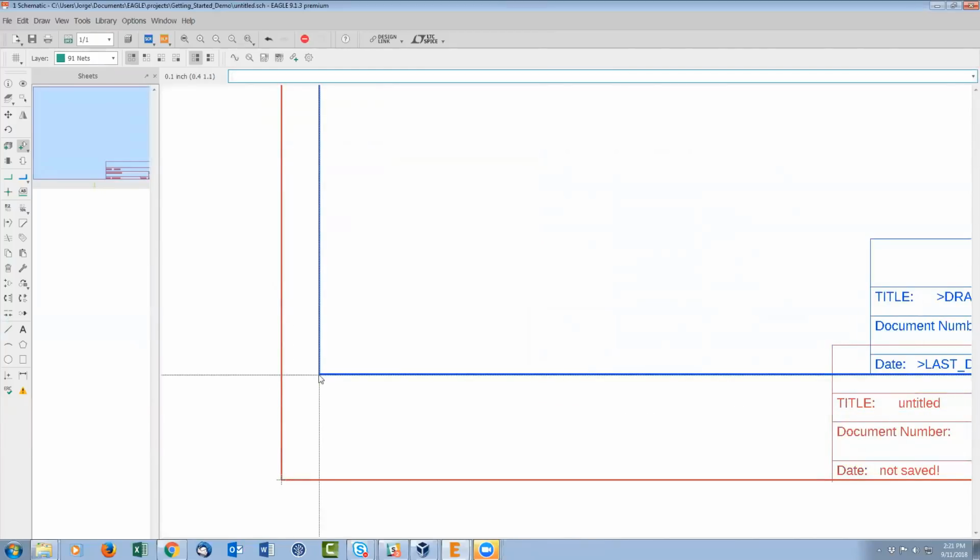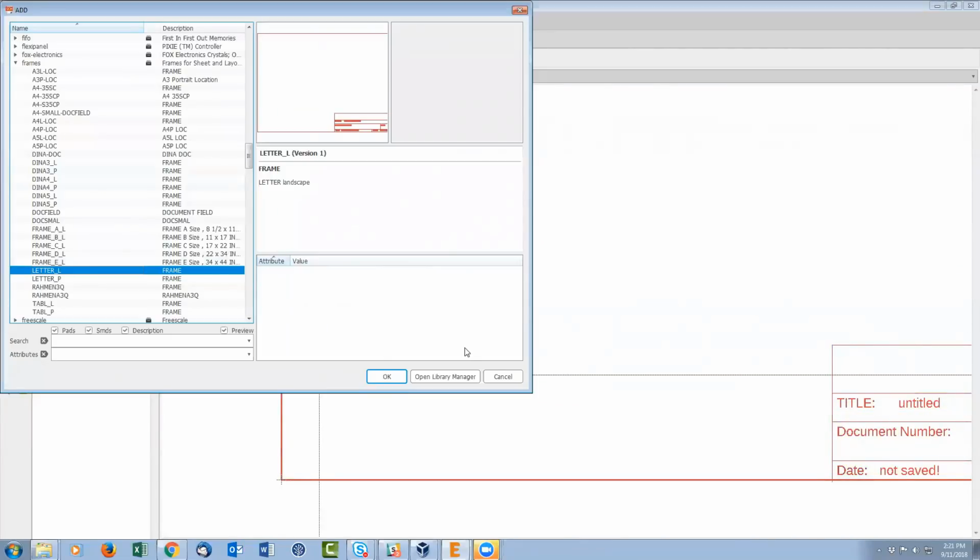Now I have my highlighting set up a little bit to be really very contrasting. So if you see the highlight color is different than what you have, don't let that alarm you. By default, you don't have the high contrast option on, but I do. So what we'll do now is we'll start searching for parts, and I'm going to take this moment to actually give a good example of how Eagle's search functionality works. Okay, so let's search for a common part, the LM555.